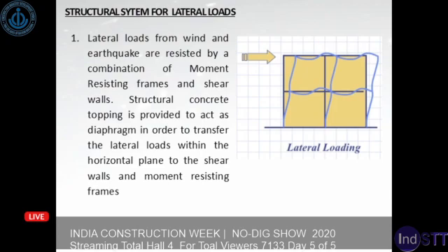The lateral loads are mainly resisted by the walls, and to some extent by the moment resisting frames. The structural concrete topping is provided to act as a diaphragm in order to transfer the lateral loads within the horizontal plane to the shear walls and moment resisting frames.